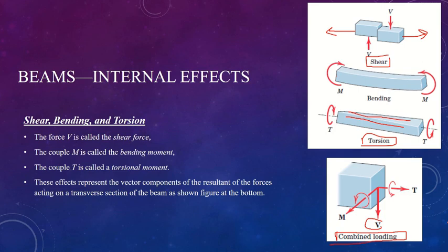Now you have to understand, if you are compartmentalizing any of these forces, or working through the calculations of any of them, they always act in pairs. This means if you have assumed the direction of one force, say a shear force, is acting downward, then its conjugate, its counterpart acting on the other side, has to be equal and opposite.